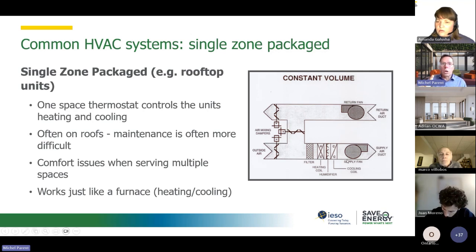So that's a single zone system. It doesn't serve multiple zones. It has one master thermostat. And that's what we often call, by the way, a switchover system. Switchover in the sense that it will provide heating when there's a heating call and cooling when there's a cooling call, so there's no duct temperature sensor in that system.